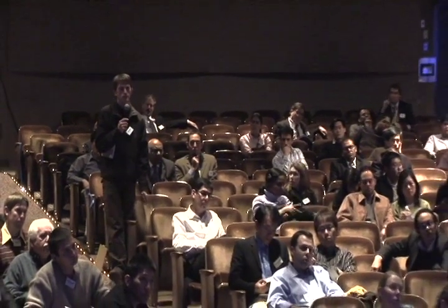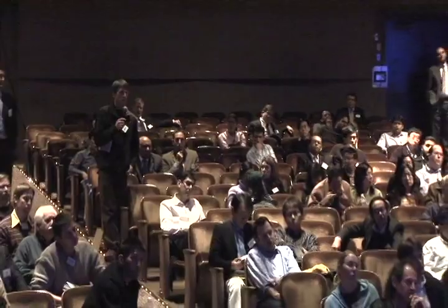Okay, we have 5 minutes before we have to leave the house. Any questions? I guess my question is, how do you get the modal analysis output from Perform? So why do you need it? The mode shapes to calculate the force pattern. I know Perform will do it for you in doing a pushover analysis. Right. But if you're doing a modal pushover analysis, you need, for each mode that you're doing the pushover for, the torsional moment as well as forces in both X and Y directions. Oh, so you want to apply the modal forces but give them some eccentricity, huh? Yeah, essentially, for the modal pushover procedure.